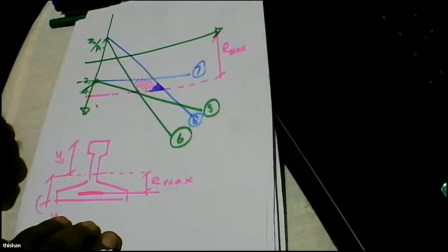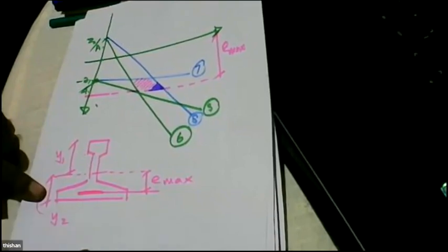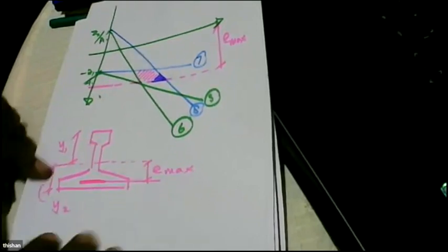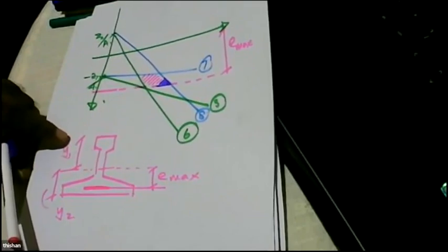But we draw the Magnel diagram for our pre-stressed concrete beam, that is this beam. For this beam, we draw the Magnel diagram, and we have to find the pre-stress also for this beam, because all the other things that come subsequently are not important for service conditions. Those are important only for the ultimate limit. So we can easily design a beam like this by drawing a Magnel diagram.